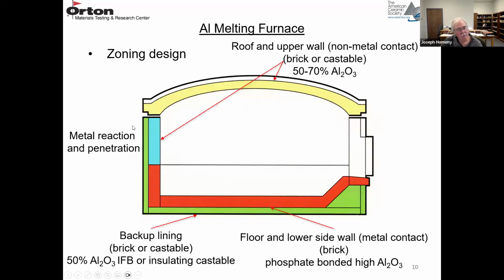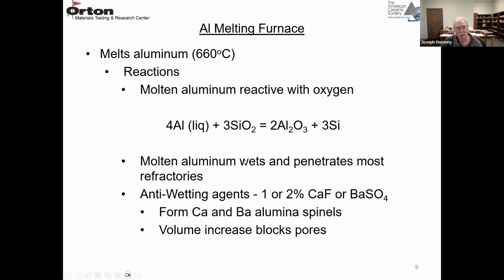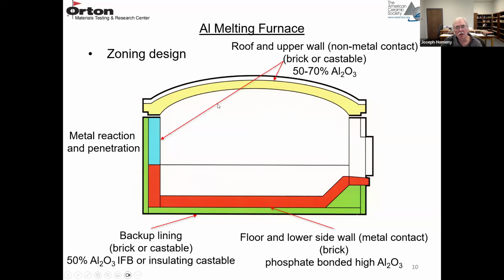So there's another reverberatory furnace. The metal reaction and penetration is the primary issue, especially this type of reaction here. So when you see this reaction, you really can't have silica in the lining of this furnace because the aluminum metal will reduce it.